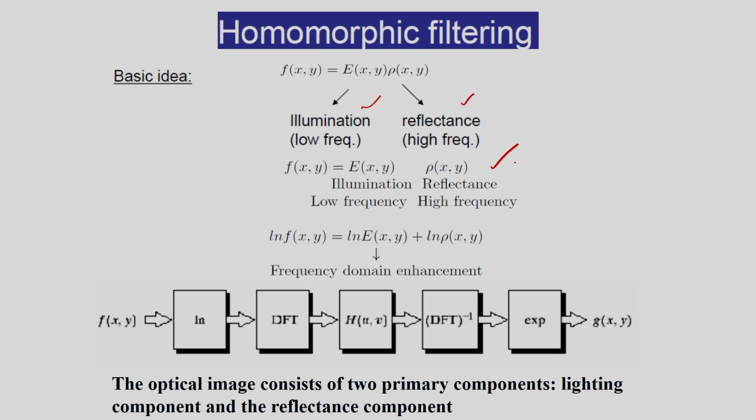So, what I am doing in this case, if you see this expression, after this I am taking the logarithm, so that the multiplication is converted into addition. And after this I am applying the frequency domain enhancement technique. So, what is the frequency domain enhancement technique? From the input image, I am taking the log, because the multiplication is converted into addition.